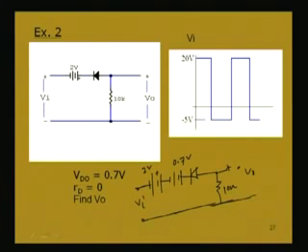So, now what will be this voltage? The voltage across these 2 points is the voltage across this resistance, so current multiplied by this resistance is the voltage. Now, in the positive half cycle, 20 volt is applied in this way. When will it be conducting? You just have to see what the potential is across these 2 points. Here it is minus, so this point is minus.